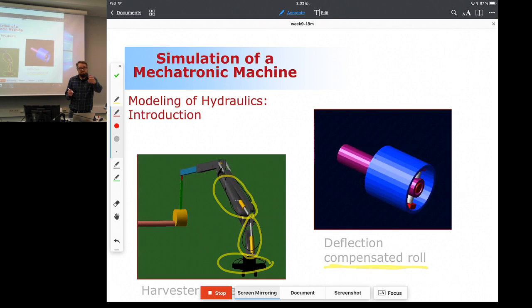It's like 200 meters long, and maybe 10 meters wide, and makes a lot of noise. The more noise, the better it is, I guess. Anyway, the machine is full of different kinds of rolls, and the rolls are pressed together. When you look at the machine in the longitudinal direction, with a roll like this, it's clear that because of gravity, the rolls will be deformed. They will be deflected in a certain way, a little bit like this.